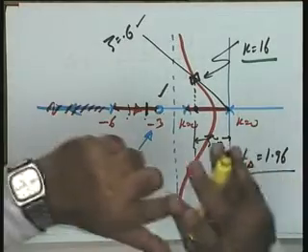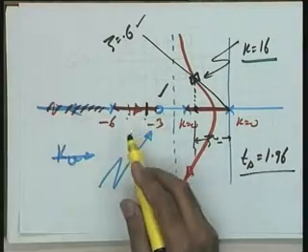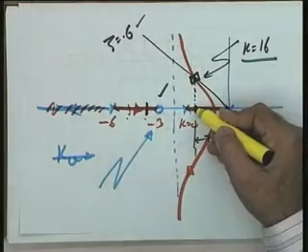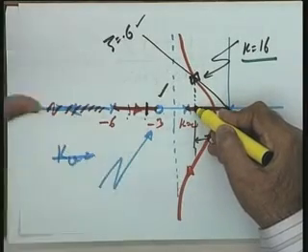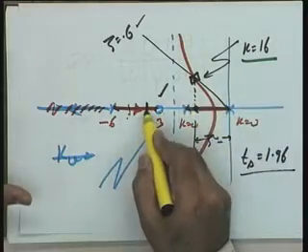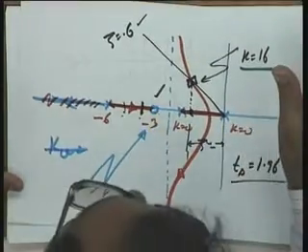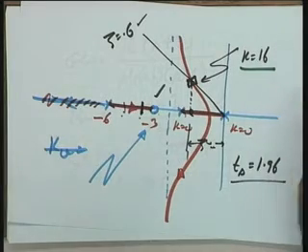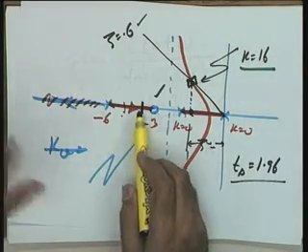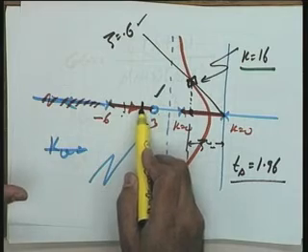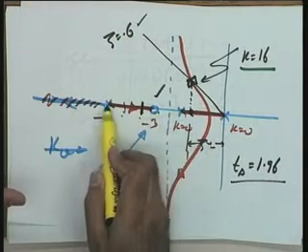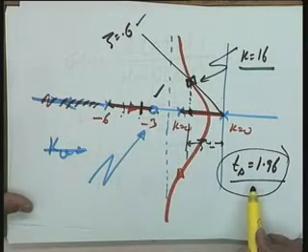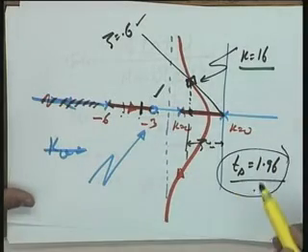So dominance condition does not mean only that the pole is far away. The dominance condition means that either the pole is far away compared to this real part, or there is a 0 close by, so that the residue at this particular pole becomes negligible. So there are two possibilities existing in this design. You have to carry out the complete design. If you are not lucky enough to get this pole close to this 0 or far away, then there is a margin available. This third pole may increase the settling time, which still may be acceptable to you.